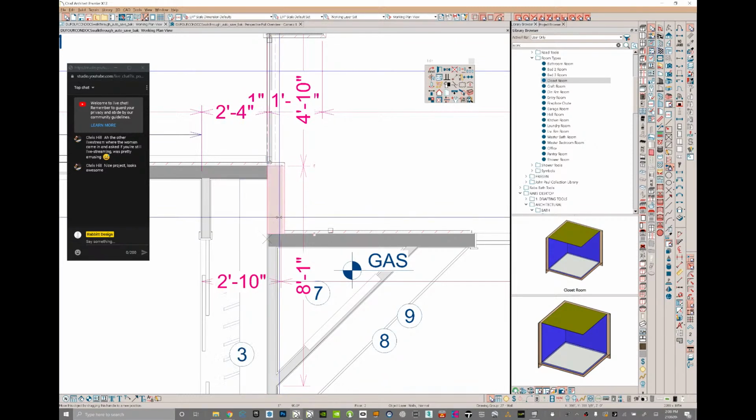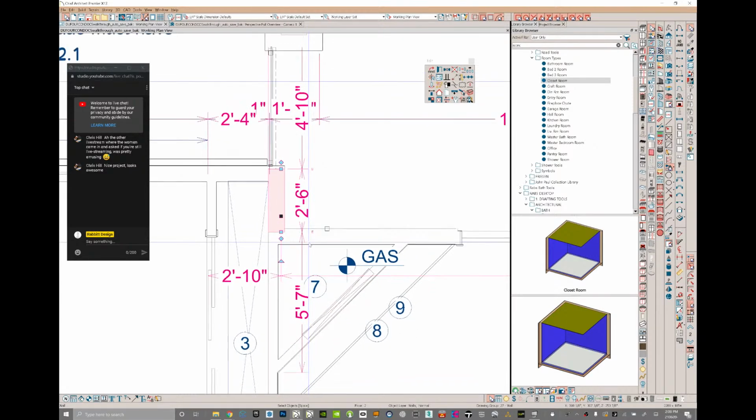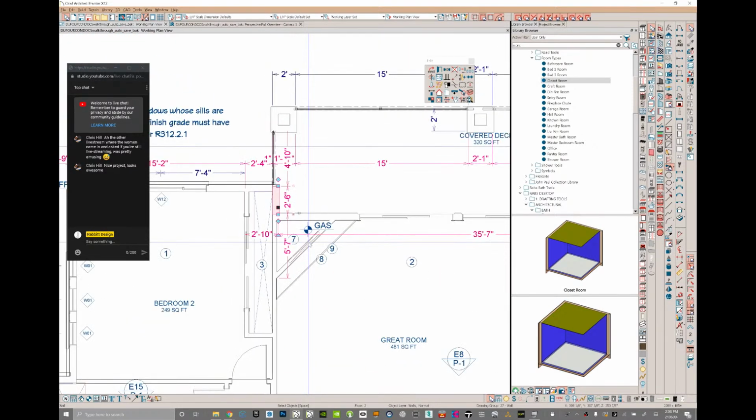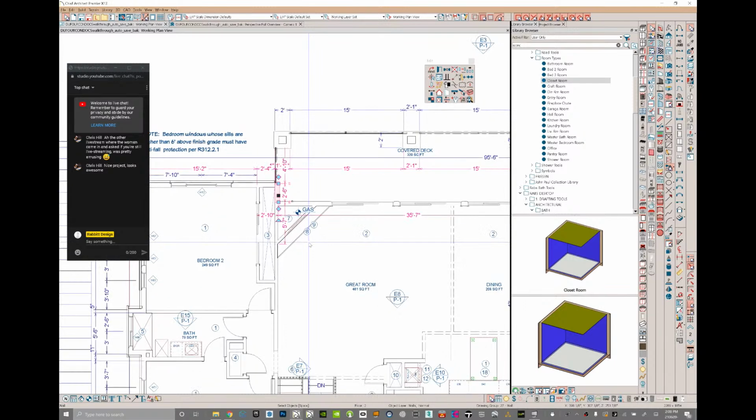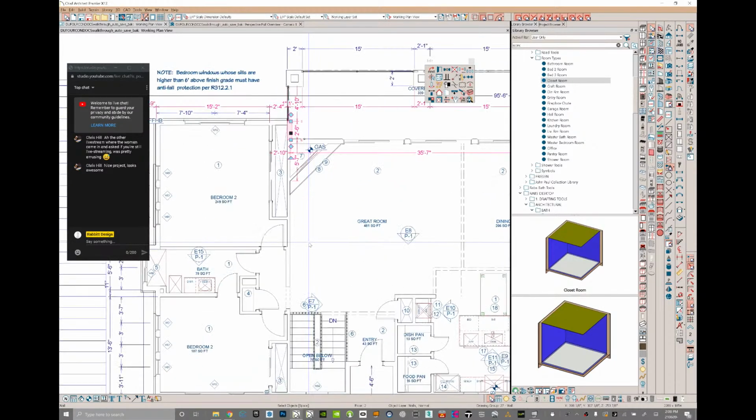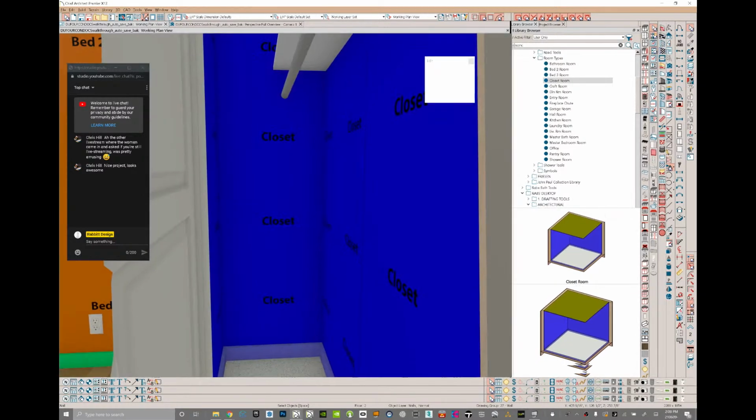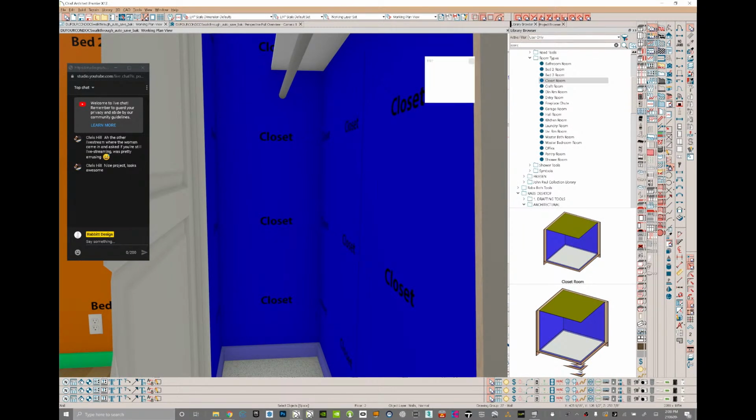That's a primary snap point. And if I go look at my snaps up here at the very top and do a little mouse over, what it should show you is that's our intersection snap. So that's where a wall intersects with another wall. Good to know that stuff. Okay, so let's navigate back to our, that should have fixed itself there right in front of us.